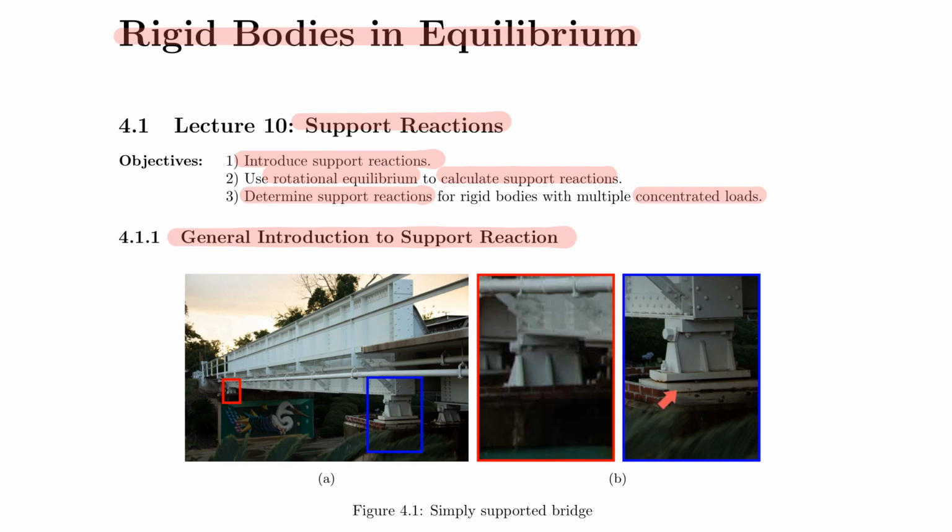You can see that on the concrete, which builds the foundation, if you will, for this type of bridge, there's a steel plate. And then on top of that steel plate, you have something that can actually rotate or move, because there is effectively a hinge here, and we'll talk more about hinges later. But you see there's a bolt here, so this entire contraption on the bottom can actually move about this point, and this part is also not connected to the bottom steel plate here.